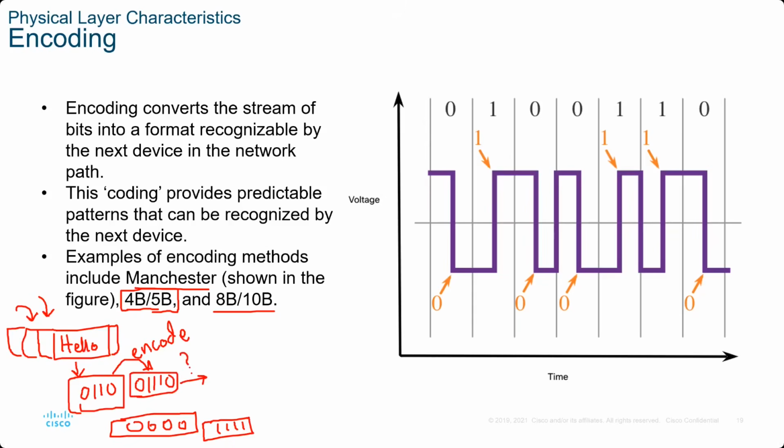What purpose does that serve? Well, it has a lot of characteristics. For one, it doesn't allow sequences of zeros and sequences of ones, which cause problems. So if you have to send a sequence of ones or a sequence of zeros, it will get first encoded into 4B/5B, and it has a pattern of, let's say, 0, 1, 1, 1, 1. Convert it to this number first.